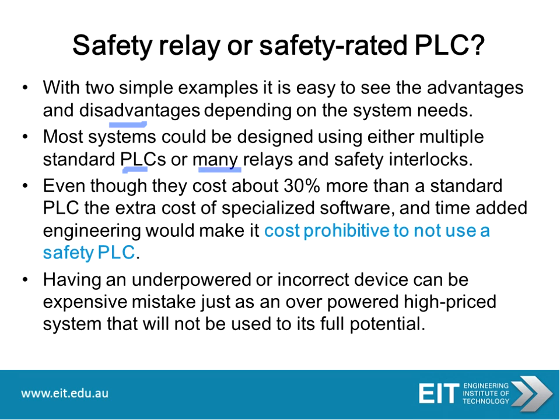Even though a safety PLC costs about 50% or more than a standard PLC, the extra cost of the specialized software and the added engineering time would make it cost prohibitive to not use a safety PLC. Having an underpowered or incorrect device can be a very expensive mistake, just as an overpowered, high-priced system that will not be used to its full potential.